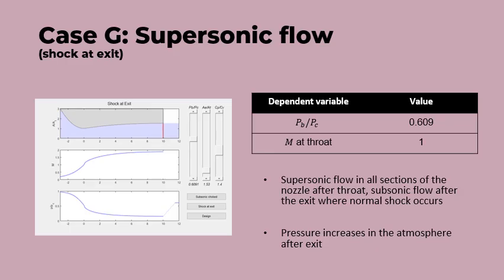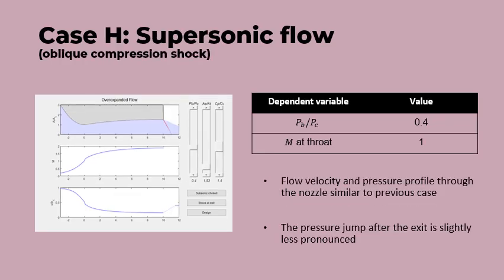We can see from the diagram that the pressure decreases through the nozzle as it accelerates and increases after the exit. At a pressure ratio of 0.4, the flow becomes overexpanded. An overexpanded flow in a ramjet leads to air expanding more than the ambient pressure, as we can see in the diagram, causing reduced thrust and potential flow instability as the air separates from the nozzle walls, reducing engine efficiency.